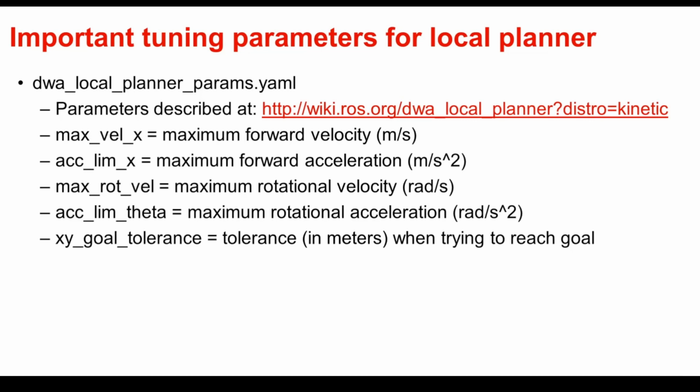If the tolerance is set to too small of a number, then if a user sets a goal that is somewhat close to an obstacle, the robot may attempt over and over to get closer to the goal while avoiding the obstacle, since it wants to avoid any collision with obstacles, causing undesired behavior instead of just stopping when it gets close enough to the goal. However, setting the tolerance too high will make the robot stop too early and not be close to its goal.